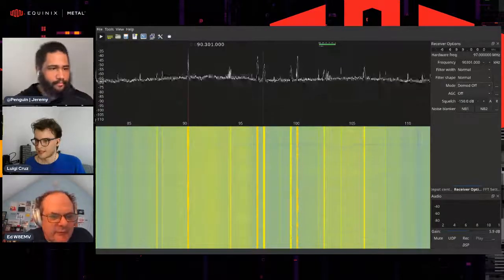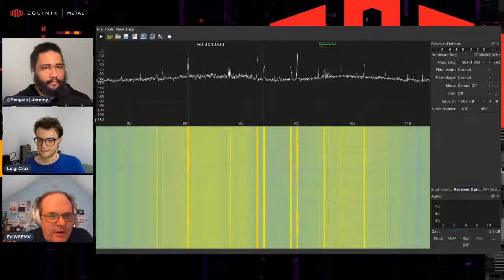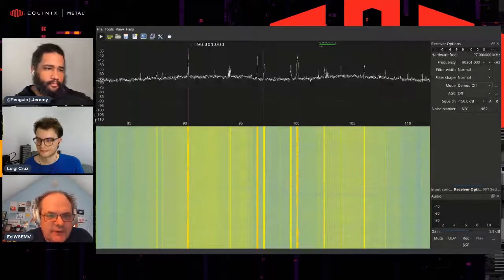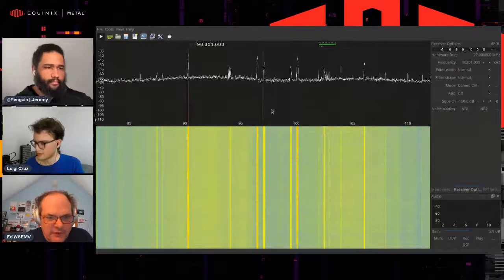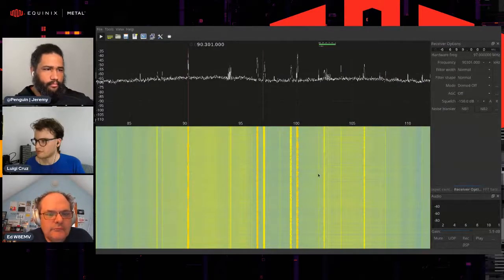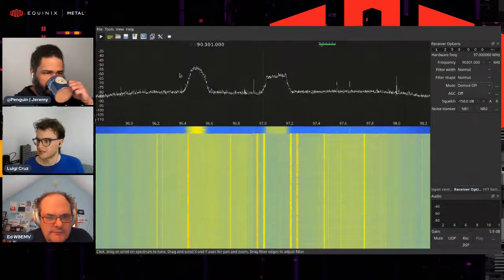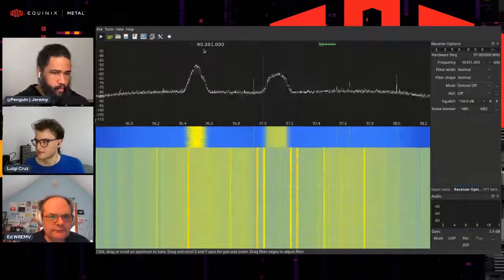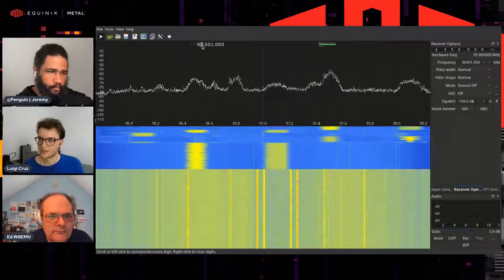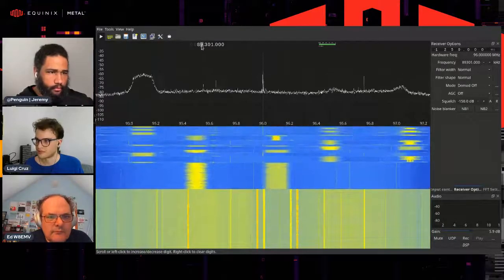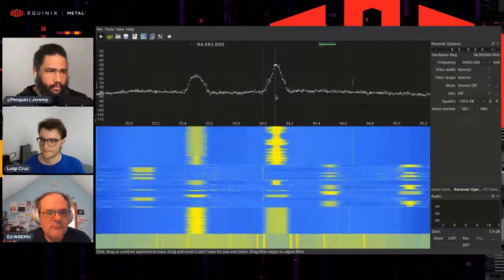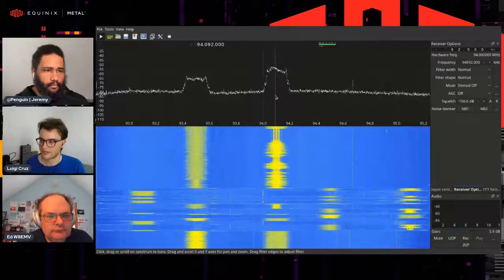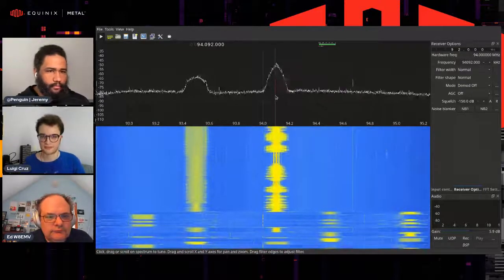So on a less powerful machine, or with a less powerful SDR, you'd see the same signals, but you wouldn't see as many of them, right? You'd have a narrower bandwidth. Yeah, if you are using an RTL-SDR, for example, you would see something like this. That is 2 radios and that's it. So you need to get in the frequency range here and toggle between the radios you need. This is 2.4 megahertz. It's the same thing, but fewer radios at the same time, fewer frequencies.